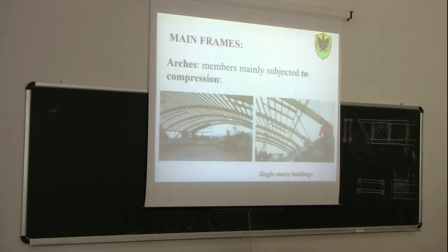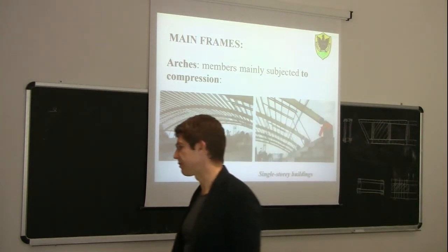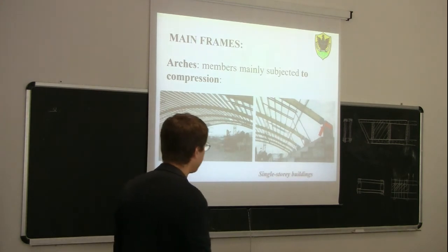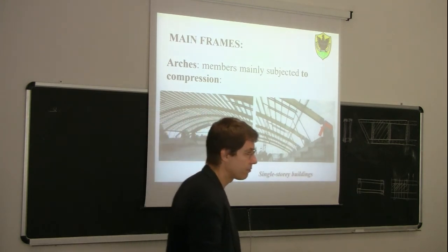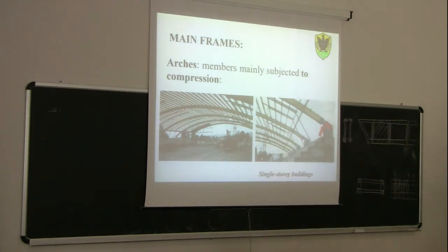Arches. So the arch is a great structural form to resist vertical loads, because in an arch the main force due to vertical loads is compression. So you can say that an arch resists the global bending due to the horizontal force through compression due to this shape. Okay?